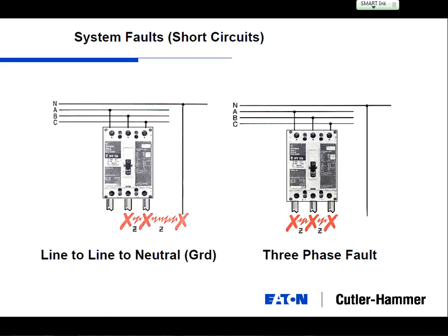So think about somebody taking a copper bar, installing a switchboard maybe, and accidentally leaving your A, B, and C phases bolted together. When they flip the switch up front, with all three phases bolted together, it is what they call a catastrophic short circuit, and it's the worst possible condition.